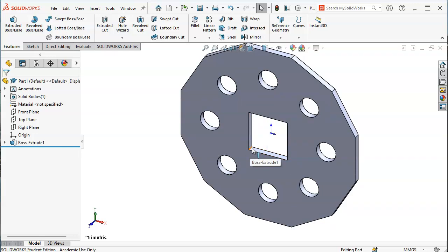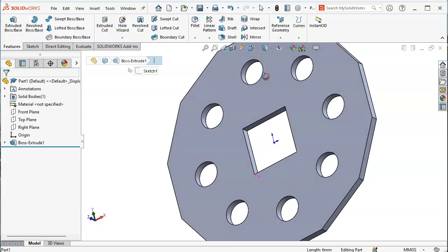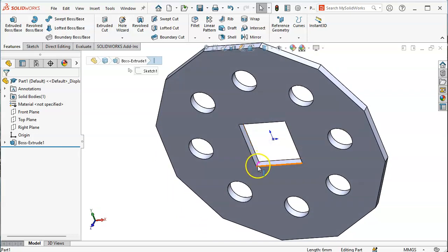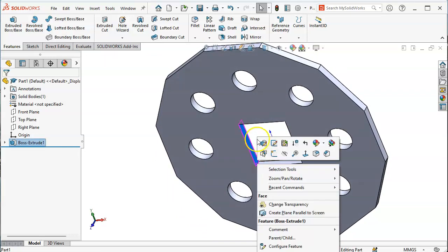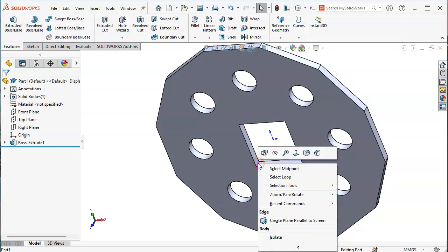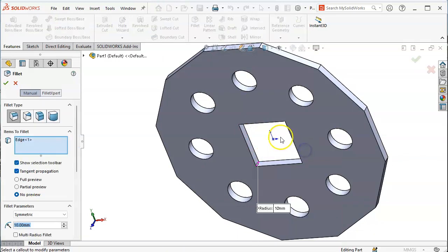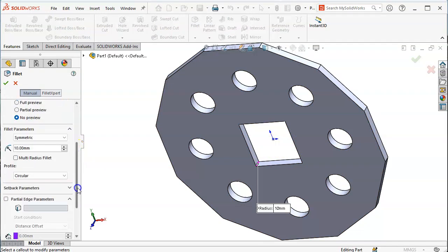These are purely optional. So one thing to point out is that we pick a corner. I got a little too much there. I got the face. And, you know, the most generous radius that we can put in there is the way to go. So maybe I'll put a 4 millimeter radius in there so that I can use a 1/4 inch tool.